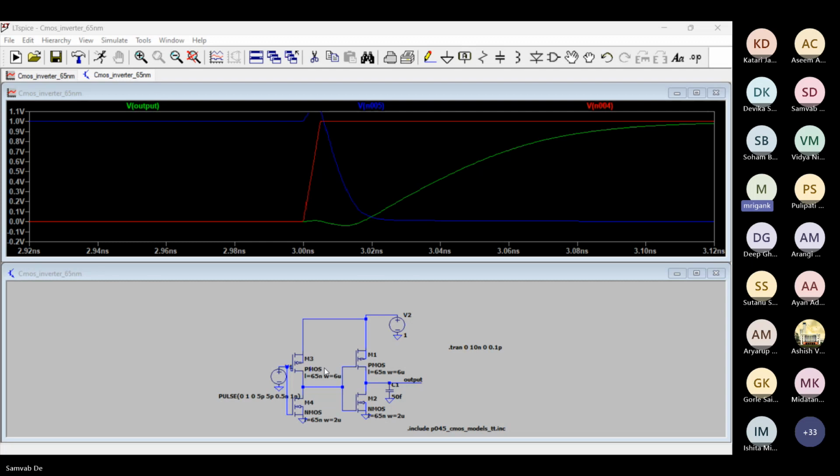That answer you should give me, because just now we also discussed what is the net capacitance at the output. We discussed that in the previous session also. So in net terms, what is the capacitance at the output? The parasitic capacitances. Which transistors are contributing to the parasitic capacitances at the output node? So both the CGD and the CGS of both the NMOS and the PMOS, the parts of them due to the Miller effect that we saw.